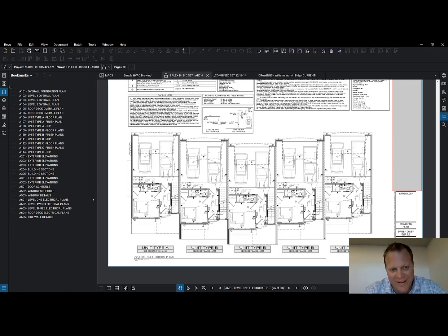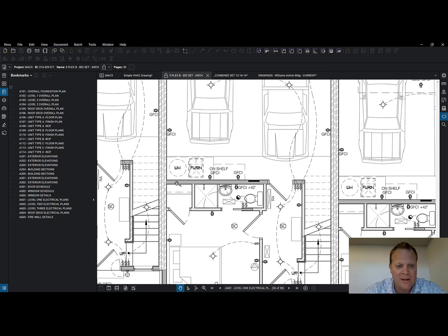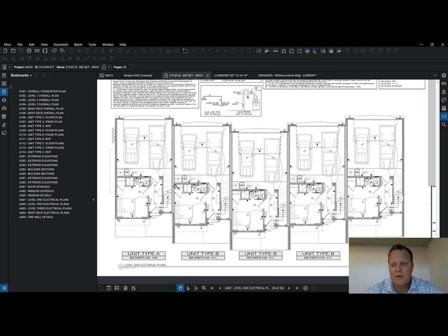Or sometimes, like I said in the past, people will use the back of a closet, and the back of a closet makes a great place for a chase sometimes. And then the person putting in the closet system sits there and shoots it together and punctures a bunch of it, or drills into it or whatever. Man, I've seen that a lot. You've got to really pay attention to and communicate where the refrigerant lines are going, and the gas and the electrical.